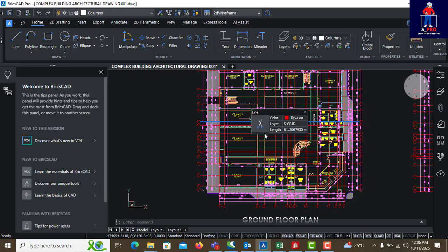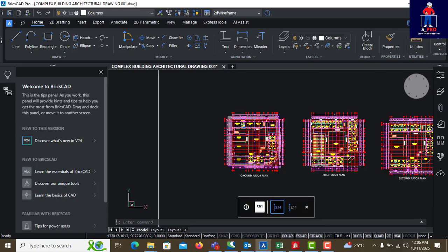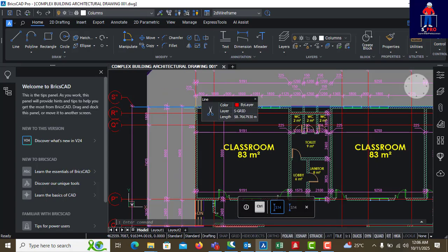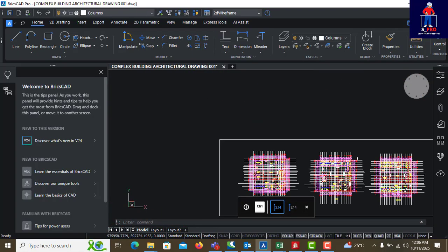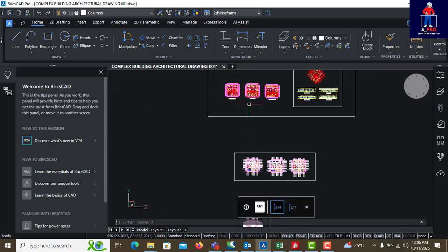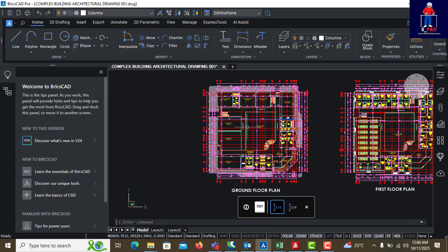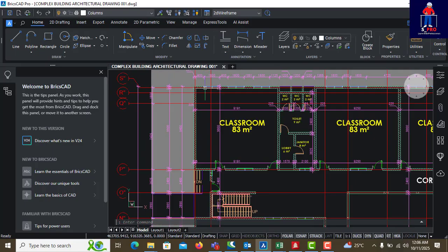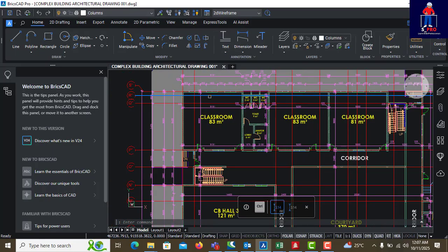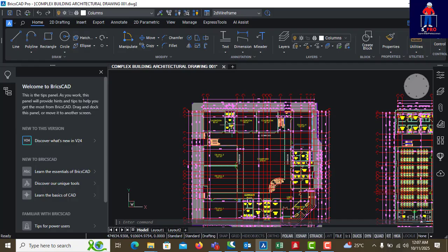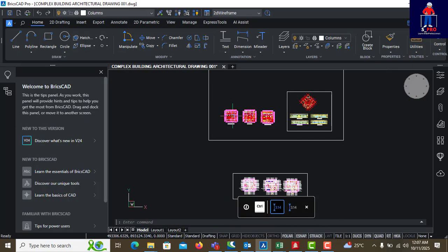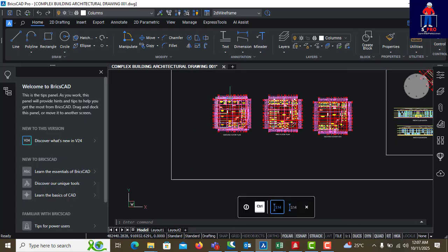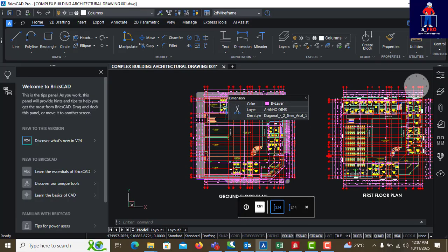So your first action point is to establish points to put your columns, which I have already done here. But before you look at what I have done here, since you already have the drawing, try your knowledge and check where you can put columns. Your own might slightly be different from mine. You must not get exactly what I have done, but provided your own will work out, then it's still good.